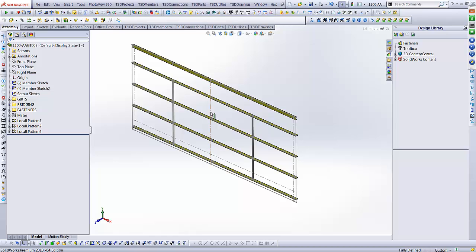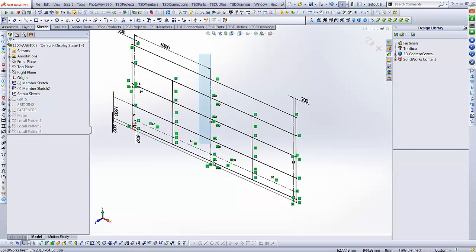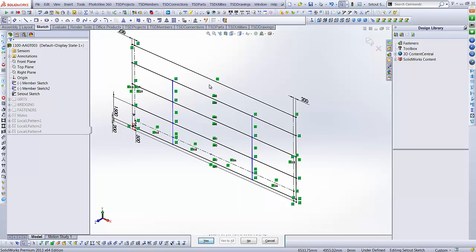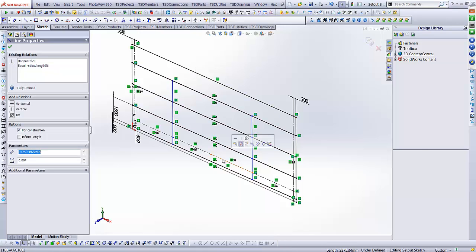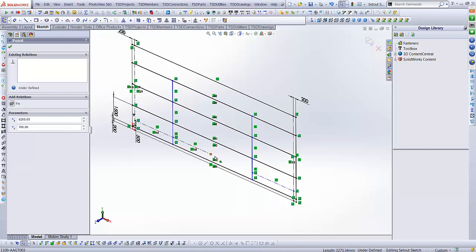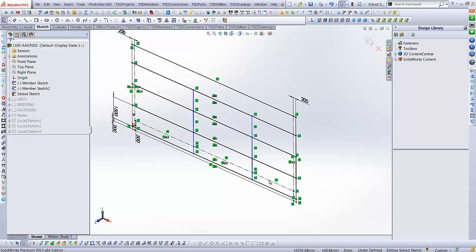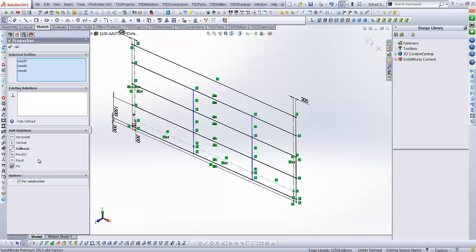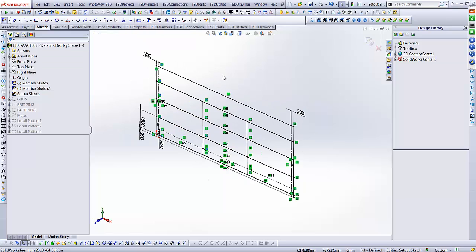Because I need the two rows of bridging, I just need to take out the center column, which is this one, because I don't want that. I want the two rows of bridging. So the center row goes. Now to get two rows of bridging, I'm grabbing the equidistance lines that I've got in here, and I'm going to line them all up so that they are equal. Alright.